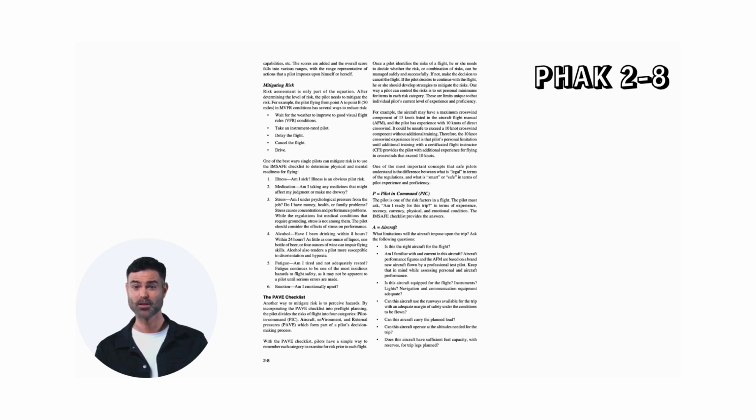One of the most important concepts that safe pilots understand is the difference between what is legal in terms of the regulations and what is smart or safe in terms of pilot experience and proficiency. P, the pilot in command, PIC. The pilot is one of the risk factors in a flight. The pilot must ask, am I ready for this trip? In terms of experience, recency, currency, physical, and emotional condition. The IMSAFE checklist provides the answers.